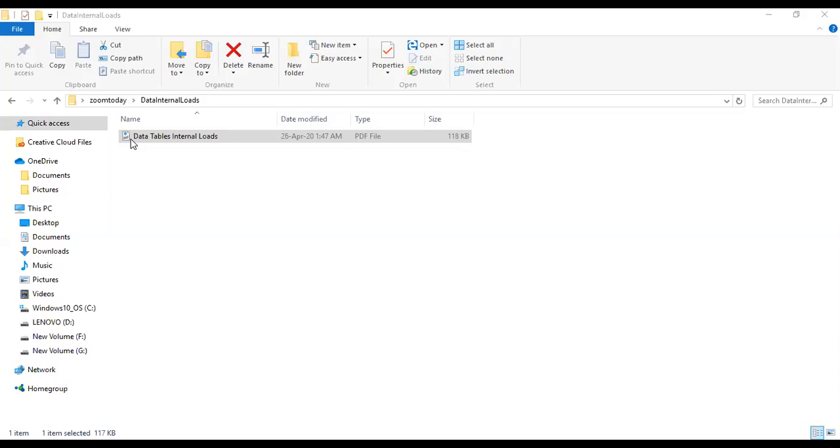So the number of occupants you can assume by yourself. If it is a residence, you can assume that there are 2 to 6 persons, and if it is an office, this is according to floor area. This is not for a residence: 2 to 6 occupants, not floor area based. But for an office, you calculate with the help of the floor area of the room.